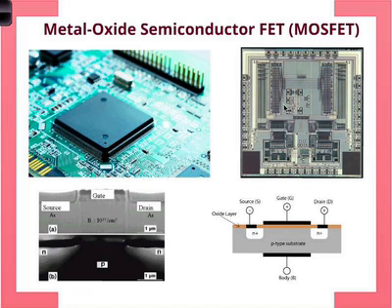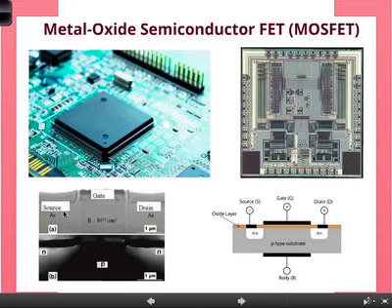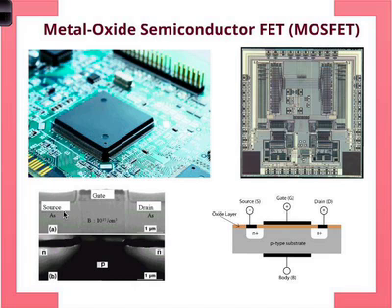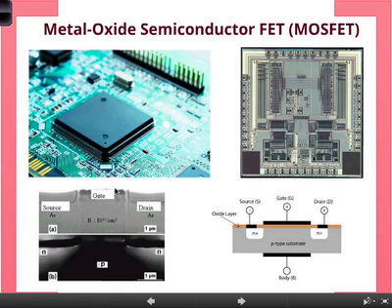So if you zoom in on one of these transistors, you can't see it with your eye, obviously, because they're very small. So you have to take a cross-section with electron microscopes and so on, and you see something like that. Okay, so that's a metal-oxide-semiconductor field-effect transistor. Again, we have three terminals. Of course, you have three terminals. We have a gate, the control, you have a drain, and you have a source.